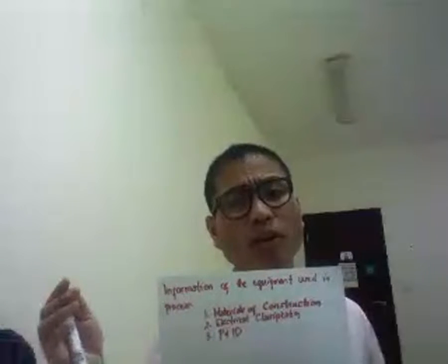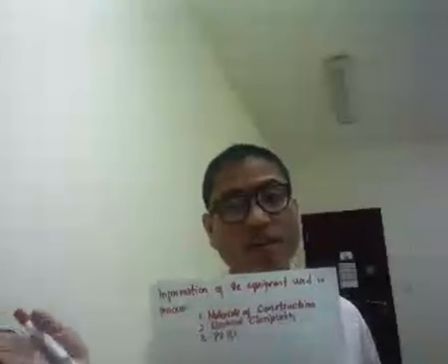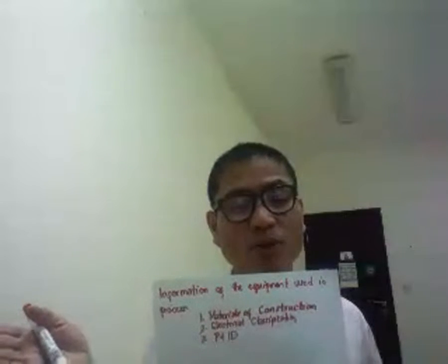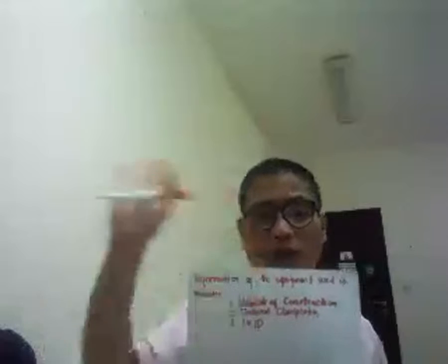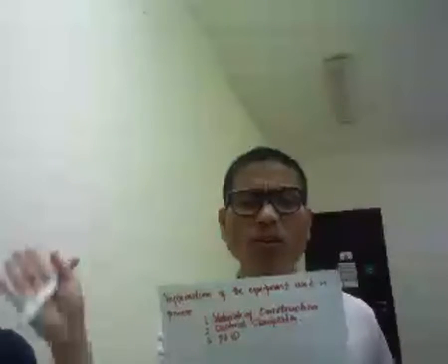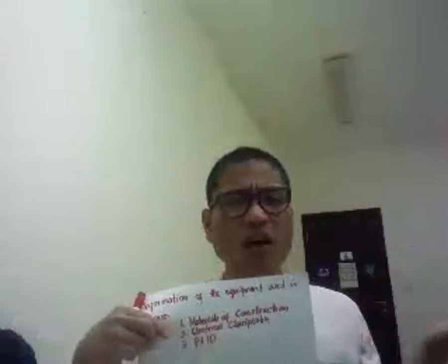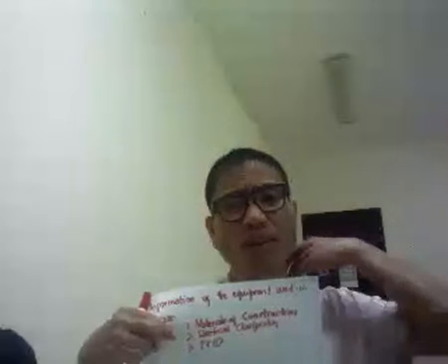whatever. Because if the valves are too high and there's no platform, then how can the maintenance personnel do the job during operation? So we need to check that one also. That should be accessible, reachable, and the orientation also of the different valves. A lot of valves, right? The check valves, the gate valves, the butterfly valves, we need to check that one.